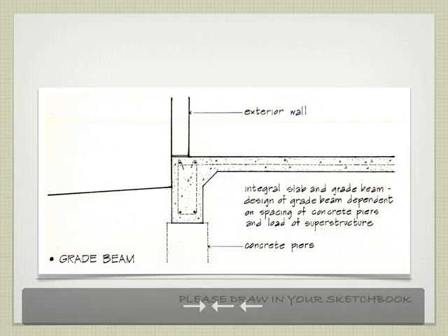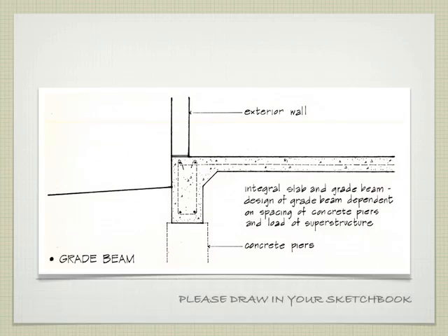Typically, and we're not seeing it here, but I'm going to try to point it out, our pile or our caisson that we poured would have rebar reinforcing that comes out of the top. That rebar reinforcing, along with, depending on the specific design, a form of a key or a keyway, which is just a depression in the concrete, would serve to interlock this with what's happening up here. So you would drill or drive your pile, and on top of that pile, on top of the fresh concrete as it's curing, the rebar would be sticking out. You would then tie that rebar into the rebar that runs along the length of the beam, right?